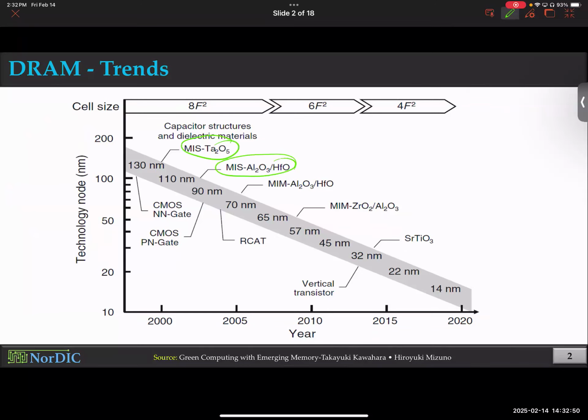Notice, what are these? Oxides, different kinds of oxides. So you're basically playing with different kinds of oxide. Oh, I lost some strength by reducing VDD because my threshold voltage didn't change. Sure, use a stronger oxide. What do I mean by stronger oxide? Oxides have their dielectric constant, K. Okay, so basically we use high K.